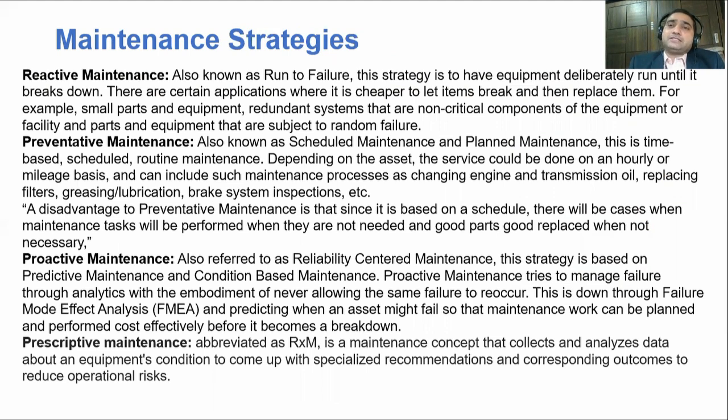and also it is done strategically for some equipment, because in certain applications or certain machines, it is okay for them to wait for their breakdown rather than keeping on doing preventive maintenance and investing a lot of time into those kinds of activities. Okay, like where you need some small parts, or there are some redundant systems which are not being much used, or some non-critical components. So for those you can do the reactive maintenance.